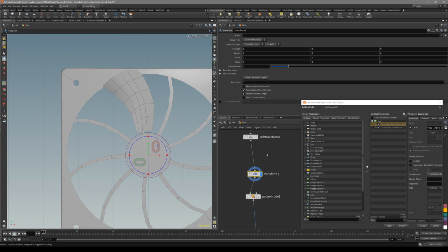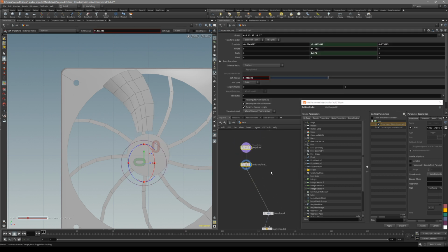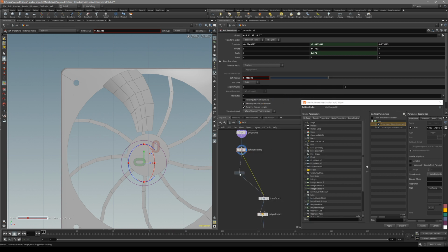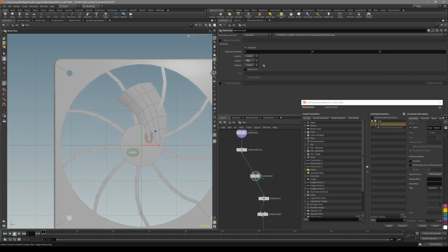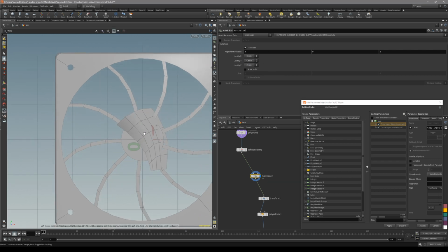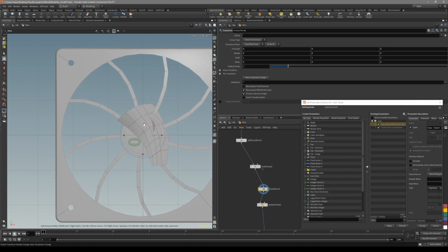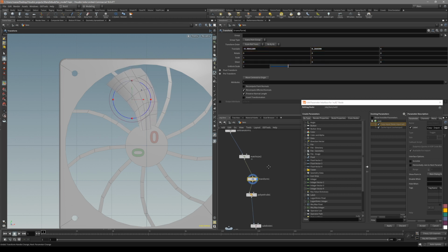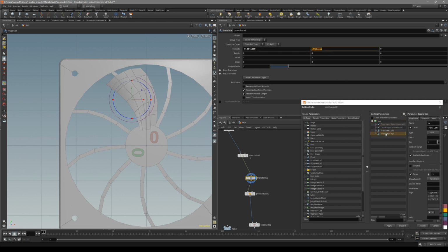But before that transform, I'm going to unify all of our objects that we pipe into the transform with match size. This is basically going to give us the base position for any of our objects. Just put it all to the center, and with the transform node, we're going to use x and y to place it where we want it. So let's pipe into translate x and y. You just select them all and drag it into it, like that.